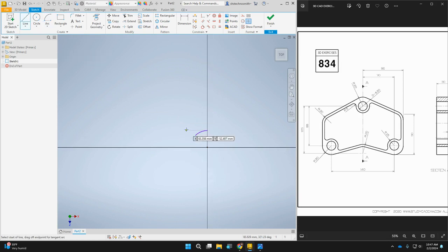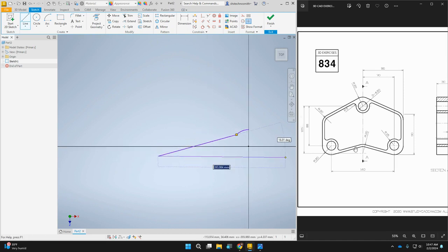So now I'm going to start to draw my shape. I'm going to come down, arc around, go up, arc over, and then finish with an arc at the top. So I've got my line command. I'm going to go off at an angle. We'll fix this relationship later. I'm going to click. Now, from here, if I look over there, this line comes down and goes right into that arc and then up. So this is a tangent arc.